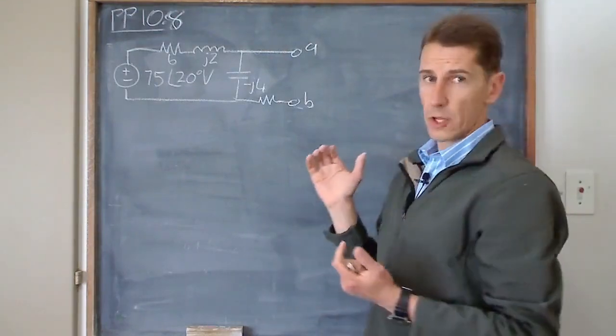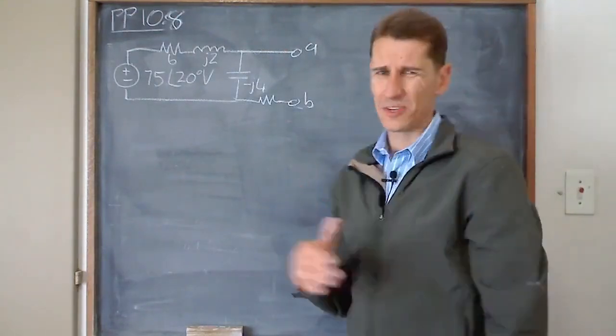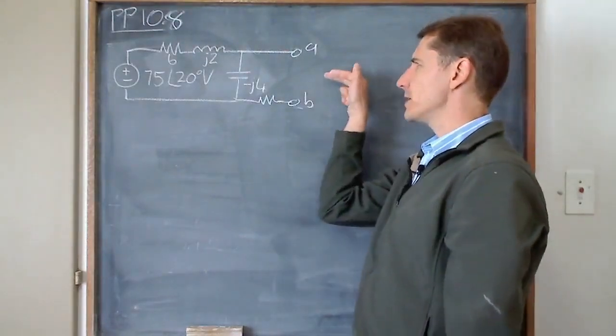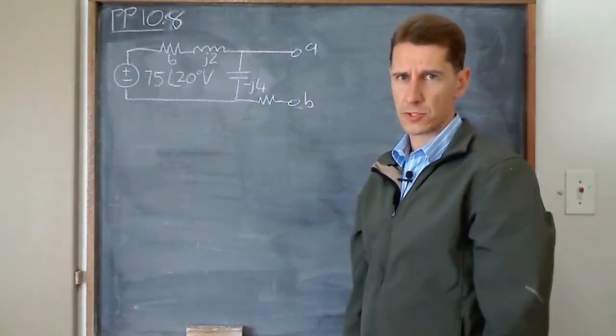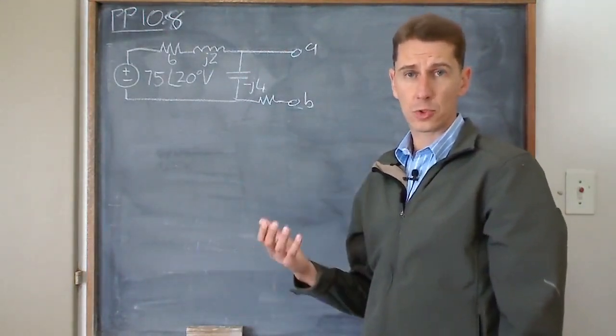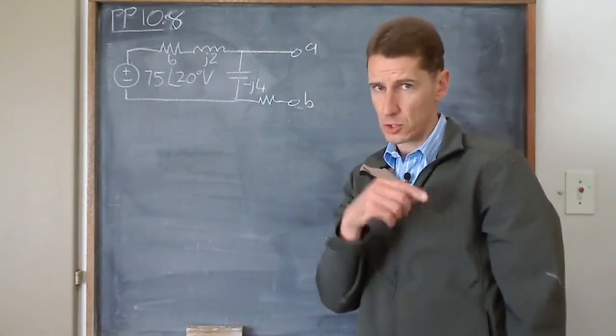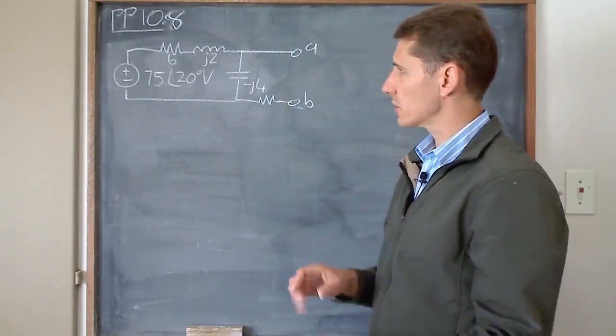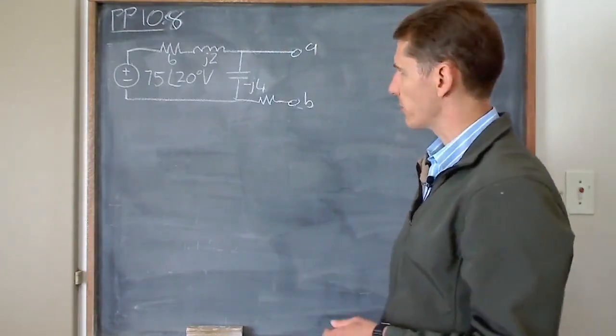If I want the Thevenin equivalent impedance, and that you did over and over again in EVN, it is the impedance that I see when I look into terminals A and B. How do you do that? You make all the independent sources zero. We're going to do an example just now where there is a dependent source in the circuit, because that's usually where the wheels come off.